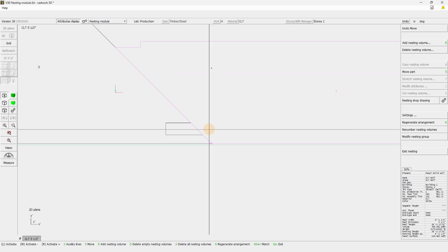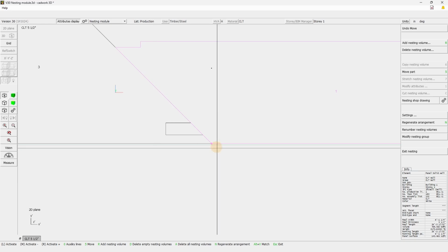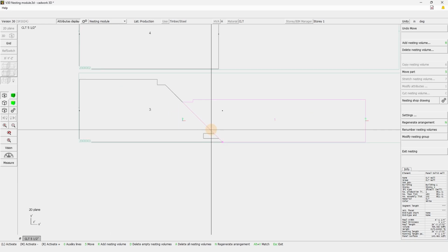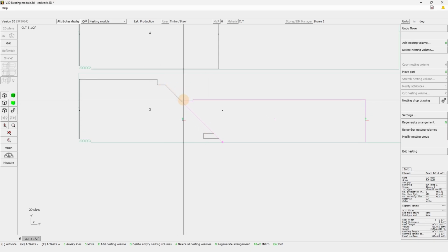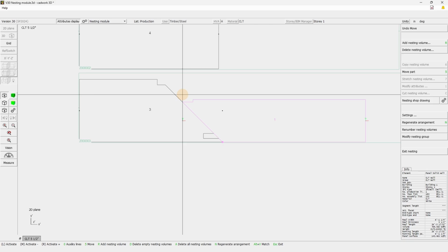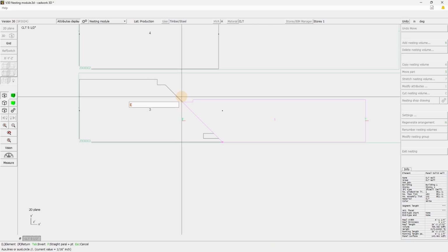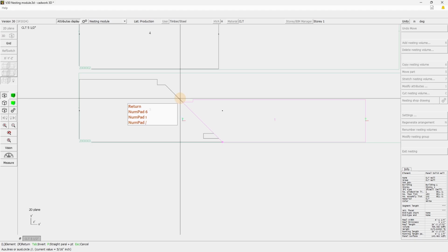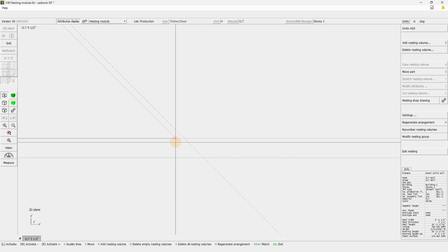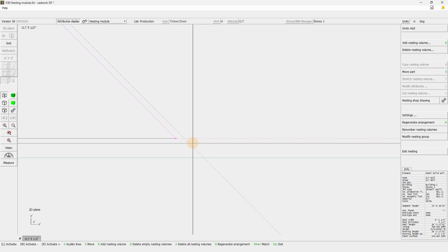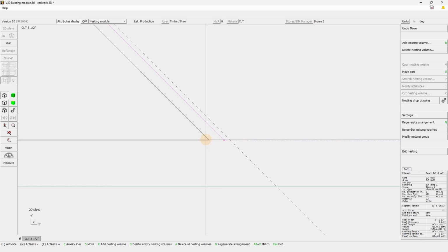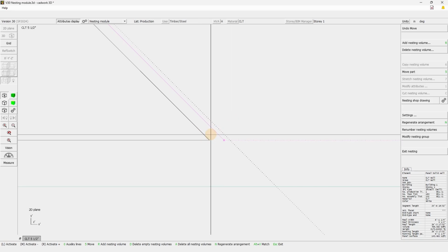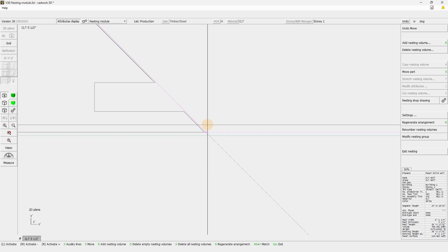So here, for example, I'm just going to use the 5/16. But in this case it might be a bit tricky because of this angle cut. And let's say that we want the 5/16 to be actually parallel to this. So here there is no easy way. The only way you would have is actually to add an actual line and make sure to move this one here. Because if you were to use the shift, you see that it's a 5/16 horizontally or vertically, but you cannot actually project it according to a certain distance. So always be careful about this.